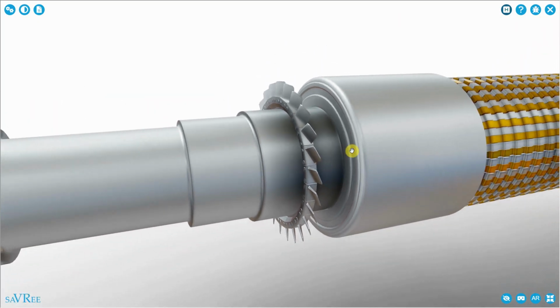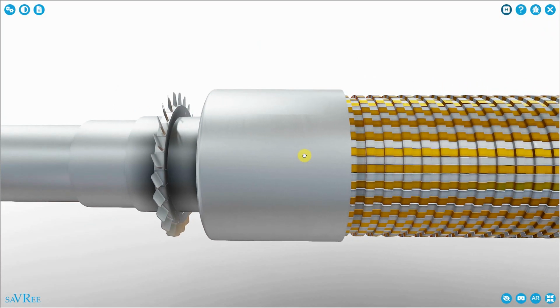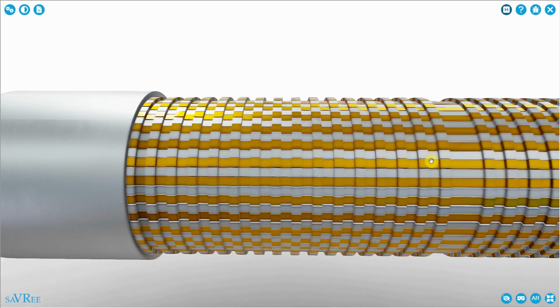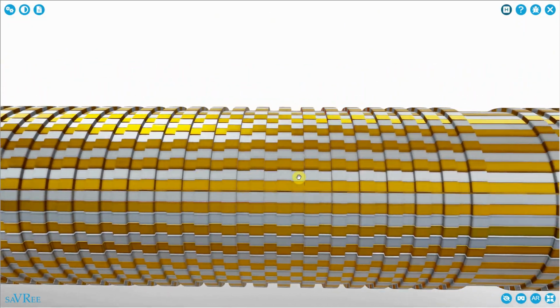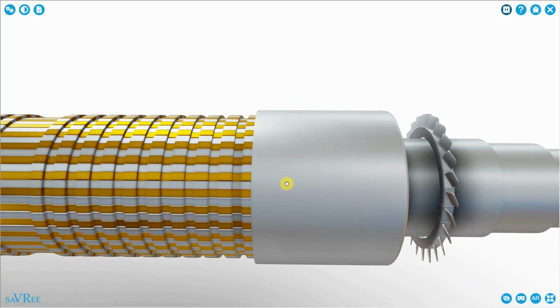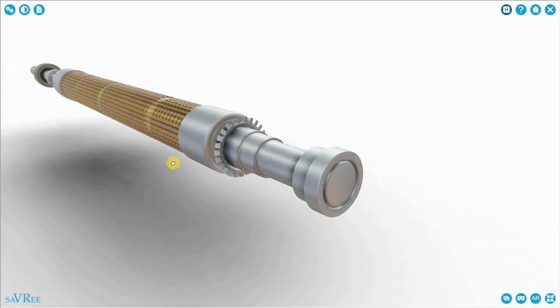We've got a retaining ring or clamping ring at this end that holds our rotor windings, or the rotor winding terminals I should say, together and helps them combat the centrifugal forces that they're going to encounter. And then we've got our windings, which are represented by these copper colours shown now. And these run from one end of the rotor to the other. This particular rotor is going to be either a 2-pole rotor or a 4-pole rotor. Notice we've got another clamping ring at this end, another fan, a place for our bearing to sit, a coupling, etc.